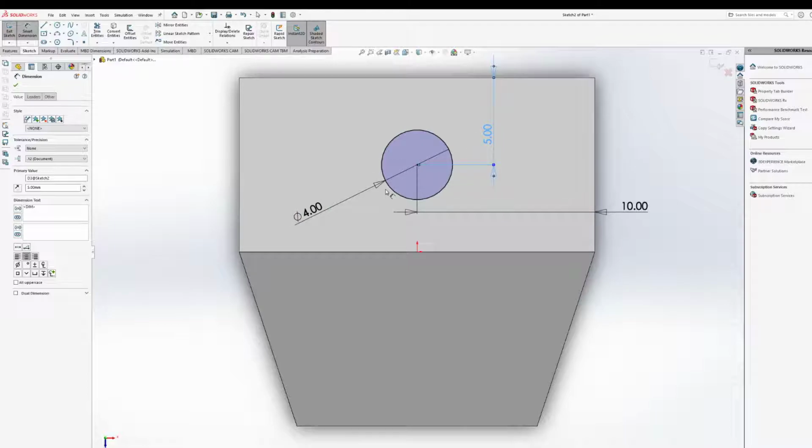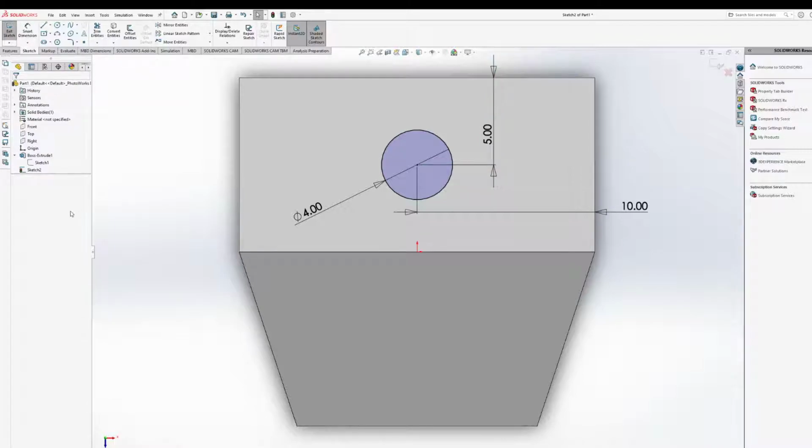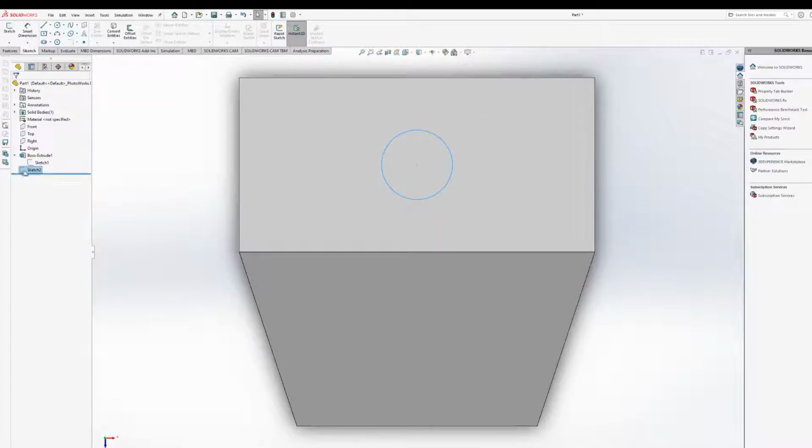And now we're actually in a much better place. As we can see, our line now is black, indicating that this shape here is fully defined. If we exit our sketch, we'll see that there's no issues with it. It's not saying it's over-defined or under-defined in any manner, so we don't have to worry about that. We're doing solid in that situation.